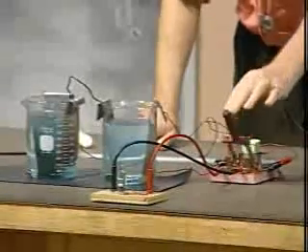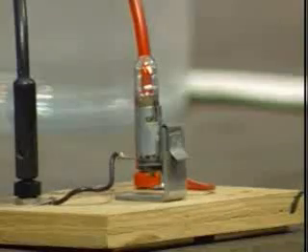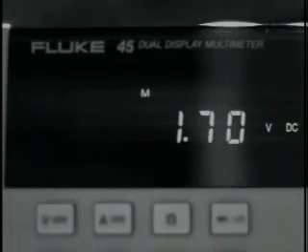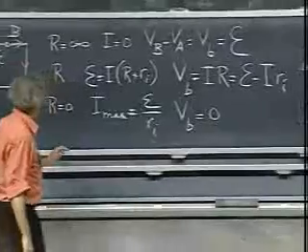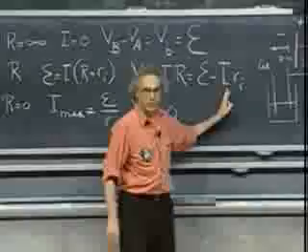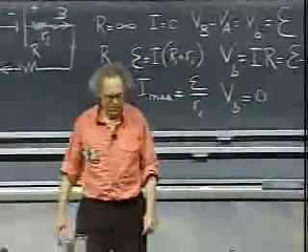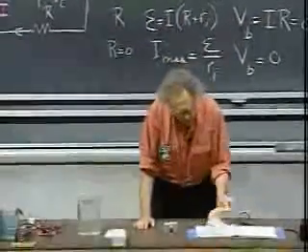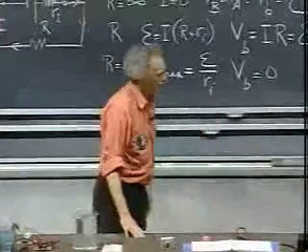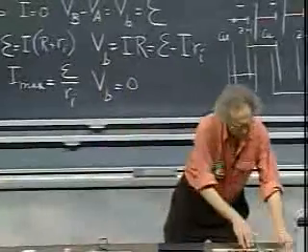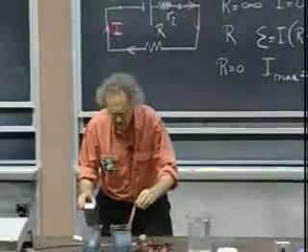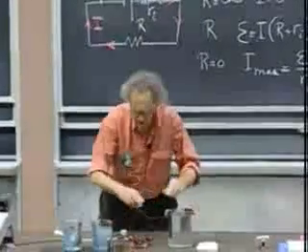So I do this now. I can see the light bulb, a little bit of light, and notice that the voltage goes down. And so this value that you measure now, V of B, is now lower than the 1.9 volts because of this term. You lose inside the battery through the internal resistance. You lose there potential difference. All right? So let's take this out because this produces a lot of smelly fumes.